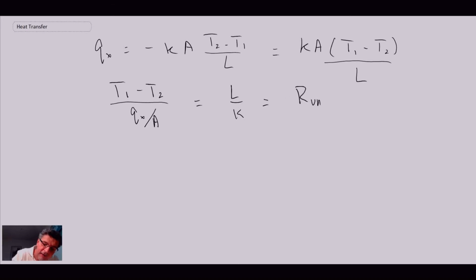So that is going to equal the R value in SI. With that, we can now solve for the length. So that's what we're after. We know this and we know that, so we can solve for it. And the length is the width or thickness of this insulation.